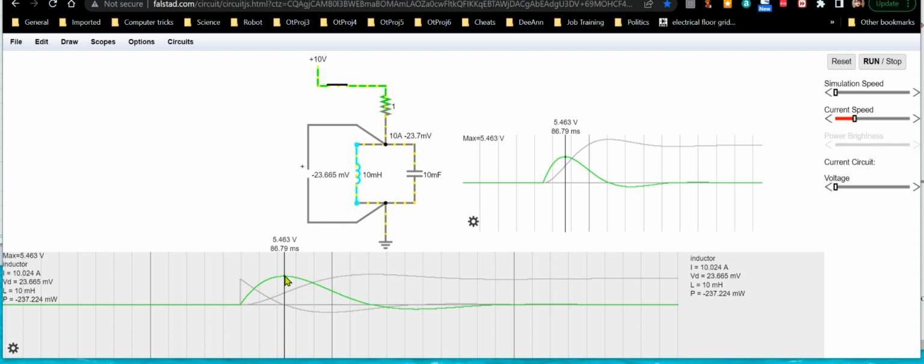But that's not just the voltage across the capacitor, it's also the voltage across the inductor. But you can see the inductor is not fully charged yet because its current hasn't hit peak. So the inductor is still charging, but that did allow for a little bit of a voltage to be set up across the capacitor. Because remember, the inductor's current starts out at zero and is slowly increasing.